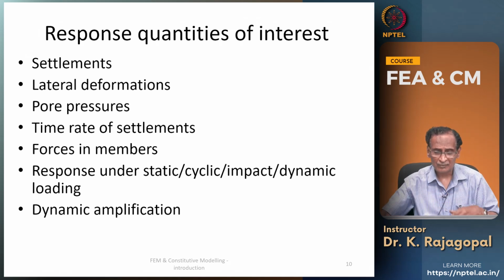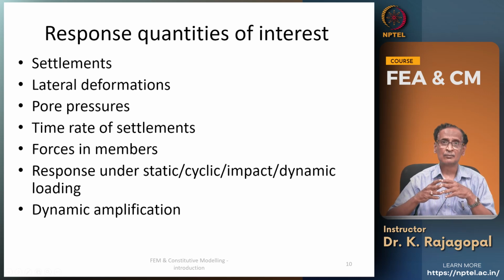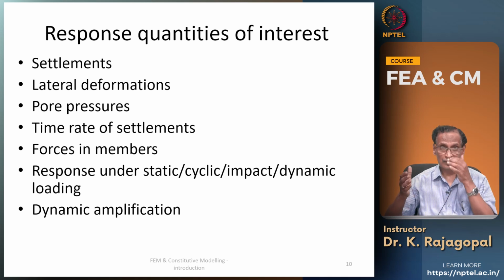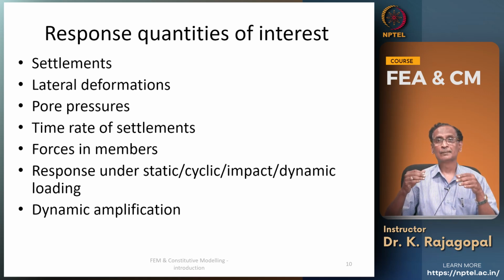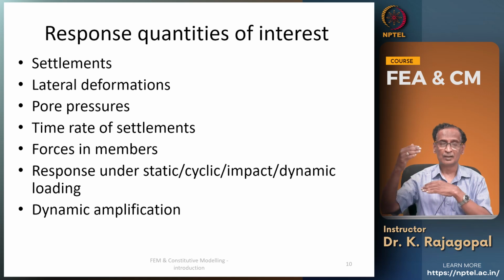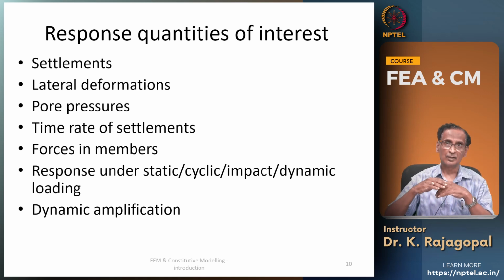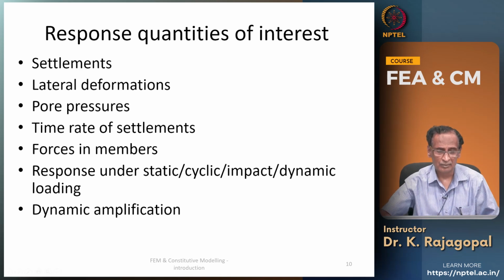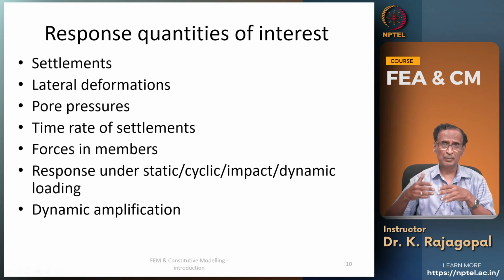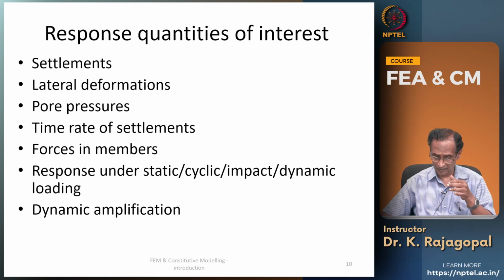When we have impact and dynamic loading, we should be concerned about the dynamic amplification. So if there is any resonance, if there is a frequency match between the structure and the loading, your response might be amplified, so that your forces may be higher and your displacements may be higher. So all these things we should be able to predict through our numerical modeling or the finite element analysis.